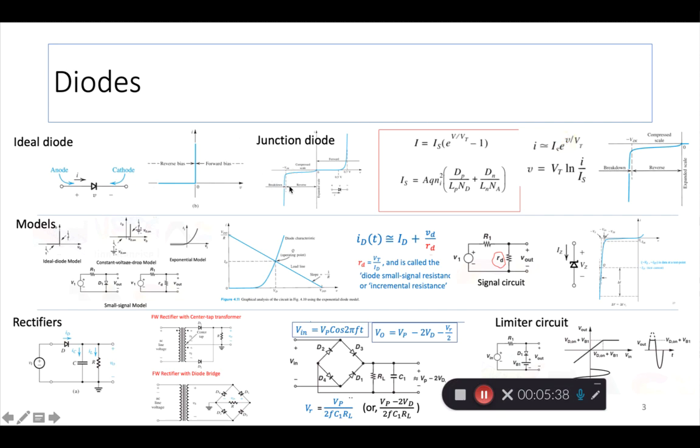but if the voltage in the reverse direction goes beyond a certain value called the breakdown voltage, or the knee voltage as they call it, Vzk, then it starts to operate in a funny fashion in the breakdown region, with a constant voltage drop but high current, right? So the forward direction is kind of mirrored in the reverse direction. This region is called the breakdown region, and we saw that there was some benefit to operating a diode in this region also. So we studied all this, and then an important relationship is obviously the diode current, right?